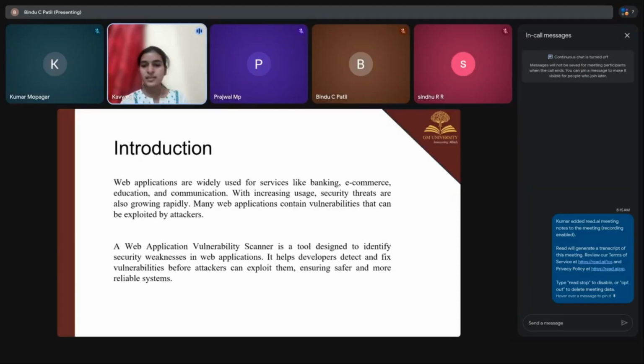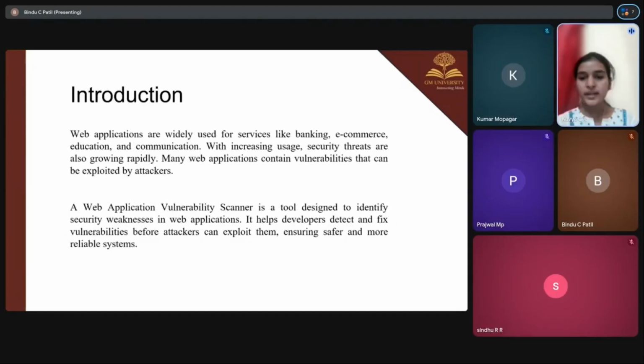Parameters like Mx and My represent the bending moment acting along different axes, while stress values indicate how much load the structure can safely carry. By interpreting these values, engineers can locate critical regions in the structure where the stress is too high or unevenly distributed. These regions are more prone to damage or failure if not addressed properly. Therefore, identifying such problem areas at the early stages is essential to ensure the reliability and safety of the overall design. Next slide.